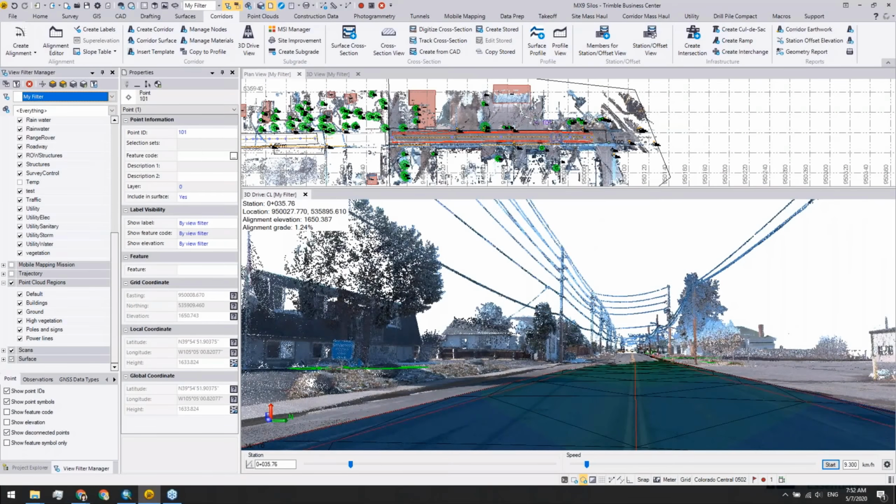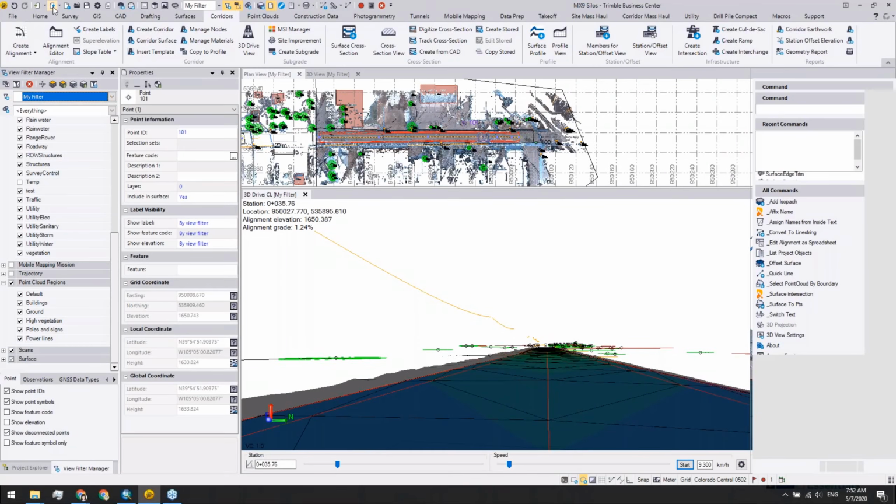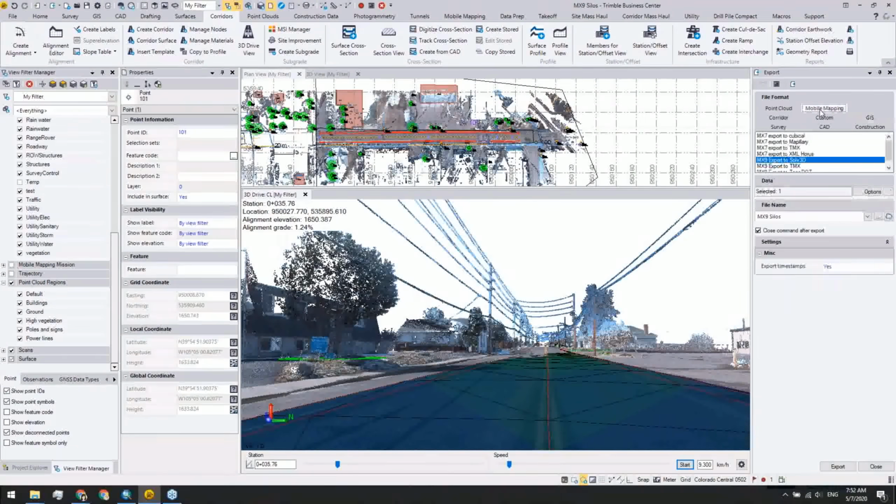Next thing, and probably also a very important thing, is the export. As you may know, TBC stores all the exporters mainly under this export command. For all the mobile mapping options, specifically if you need to export MX9 trajectory, imagery, and point clouds into third-party mobile mapping processing packages, you can go to this mobile mapping tab and choose export to Soft3D, TMX, Trimble MX, or TopoDot.